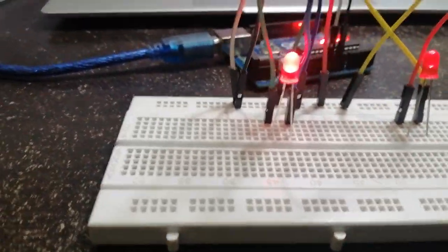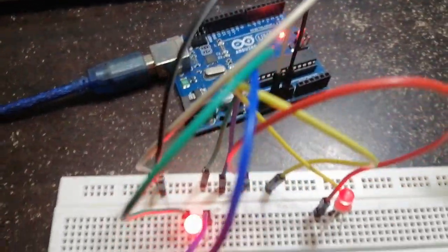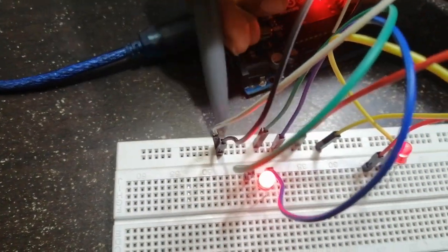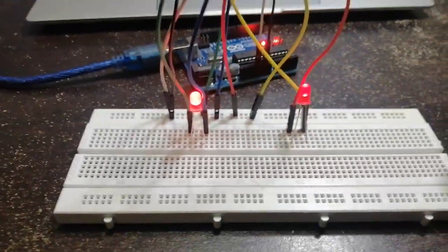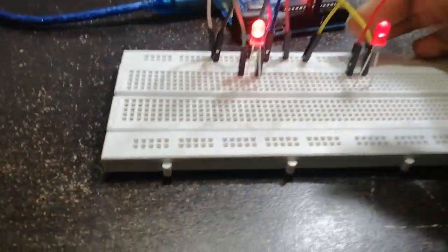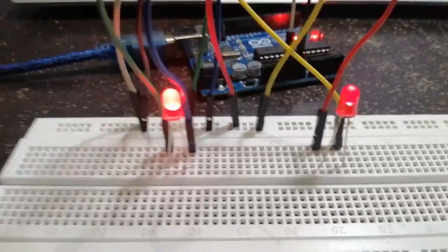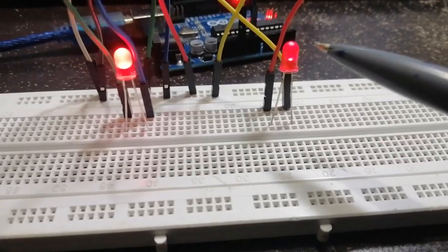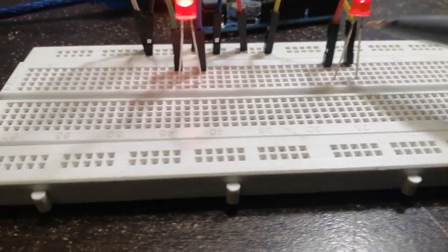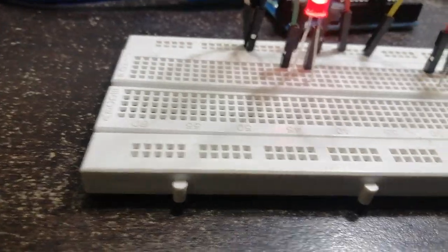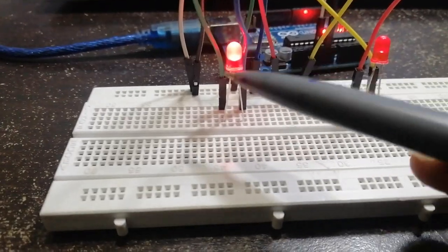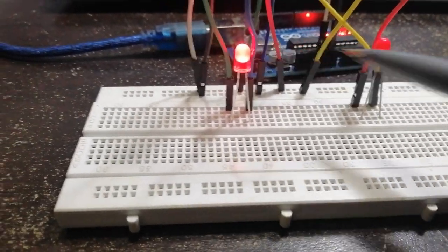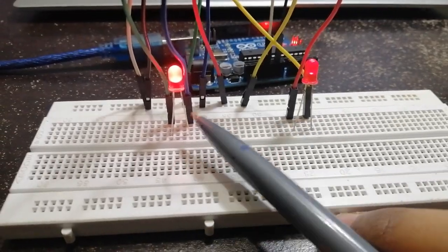Okay, now I've finished the parallel circuit, and the power connections are going from this one. This is the positive side and this is the negative side. So each LED is individually getting 5 volts. This one's glowing bright, this one's not glowing so bright because I think the cables aren't connected properly. I'll take a look at that later. But what it's supposed to do is they both will glow with the same brightness as they're getting the same voltage, and the voltage does not divide between them.